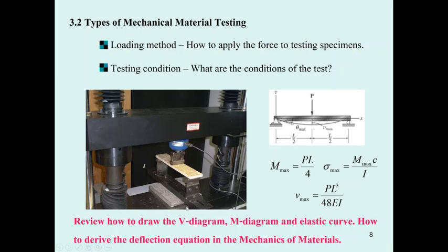Anyway, I'd like to assign you to go back and try to draw the shear diagram, moment diagram, and also the elastic curve of this beam. And I'd like you to derive the equation for the deflection of this beam also, to get more in depth or to review your mechanical property, which is the basis for the material testing.